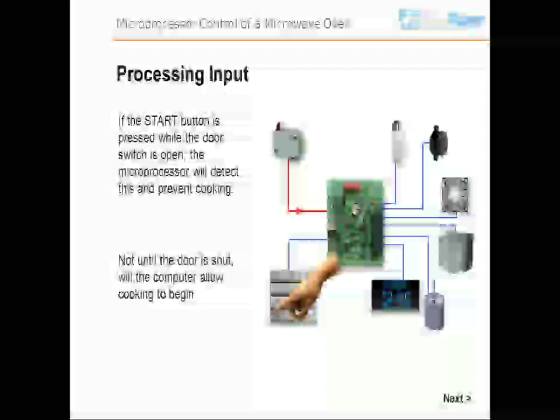Processing input. If the start button is pressed while the door switch is open, the microprocessor will detect this and prevent cooking. Not until the door is shut will the computer allow cooking to begin.